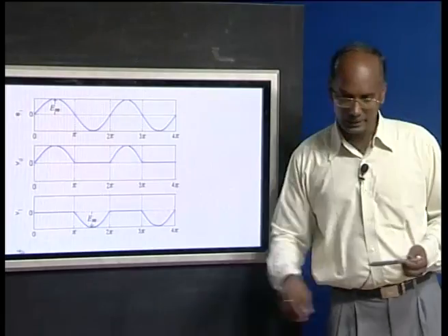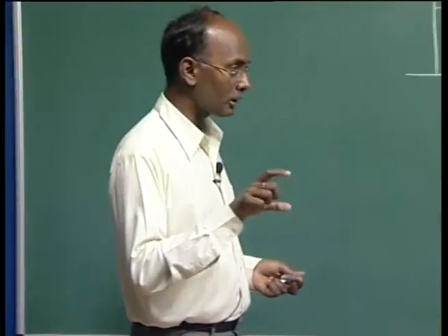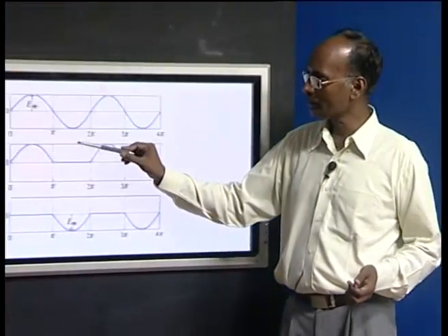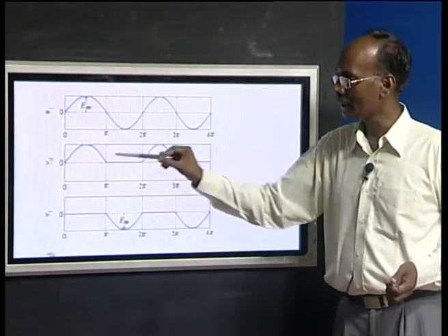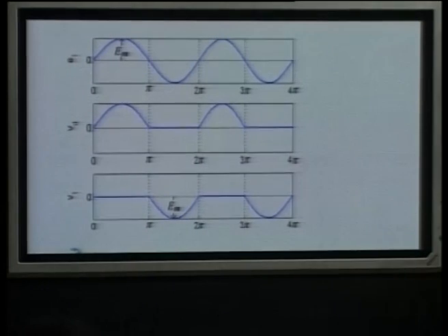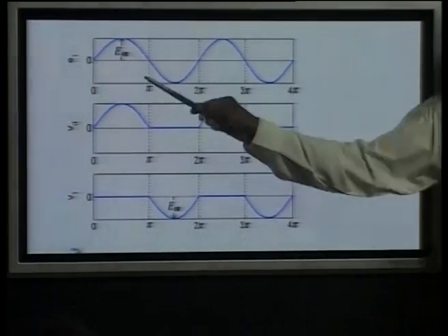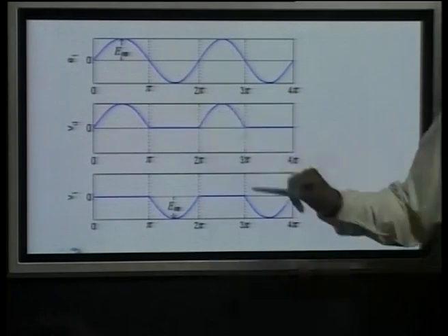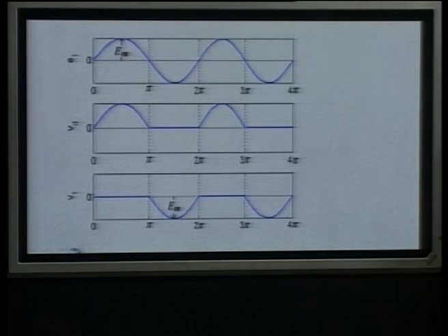So, this is the instantaneous voltage appearing at the output of this rectifier circuit, and to calculate the average voltage, you just have to integrate over the complete cycle. Here you can see the pulse number is unity, because in one cycle we get only one pulse of the DC output. So, the number P in this case is unity, 1.